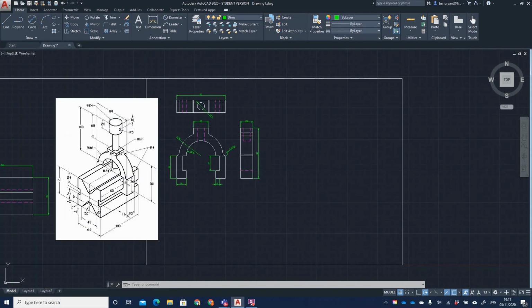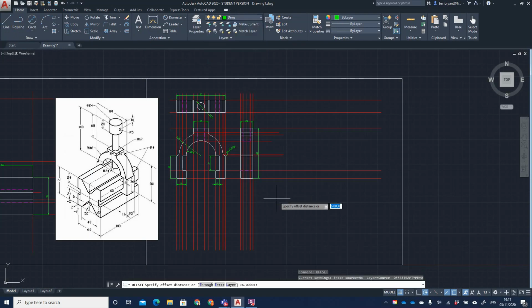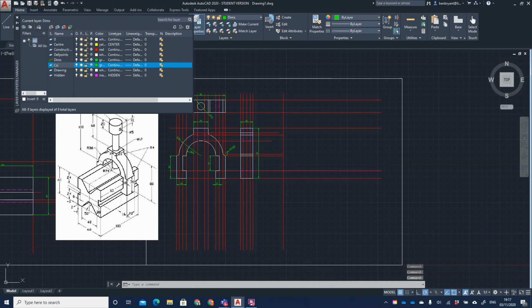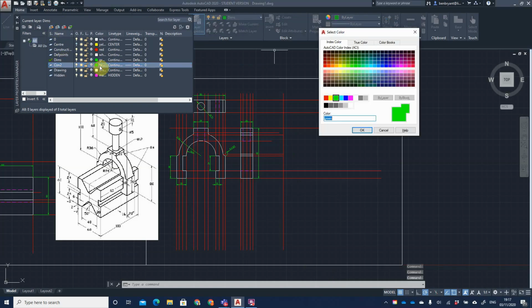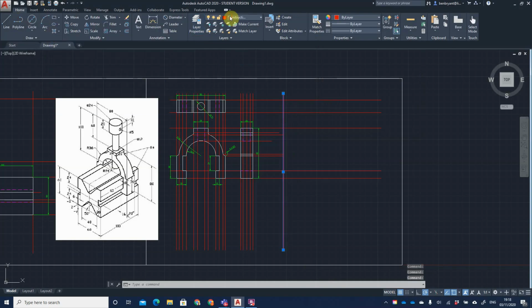The last part, because I have a small screw now, actually it's no point putting it on a separate A3 page. So I'm just going to turn on my construction lines again. Do a nice offset. This time I'm going to say about 50 millimeters away from my edge, and put it nice and evenly away. You could actually change the color if you wanted. So you could say, actually, I'm going to make another layer, call it con 2, and change the color, like blue. And what you could do is change that to your second construction layer and then turn off your original.